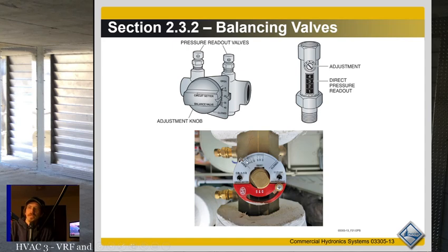So the only way you're going to get good control out of this ball valve is if it has a smaller port in it in the piping. Otherwise, most of your balancing happens at the last bit of its travel. So if you need close to the full flow through the piping, right? If you've got a piece of equipment that has a 3/4 connection and needs to flow almost the full 6-ish GPM or whatever that 3/4 inch can handle, then a 3/4 balancing valve is not really big enough. Alright, so you might need a 1-inch balancing valve for a connection size of 3/4 or something like that.